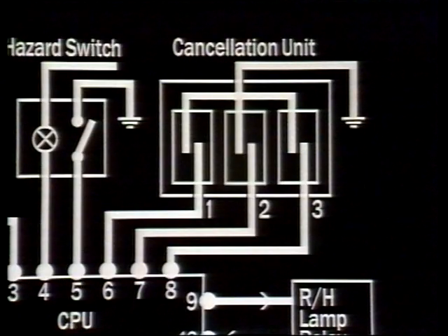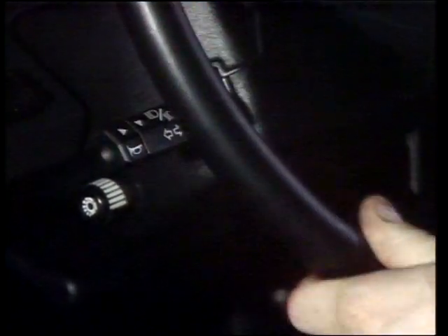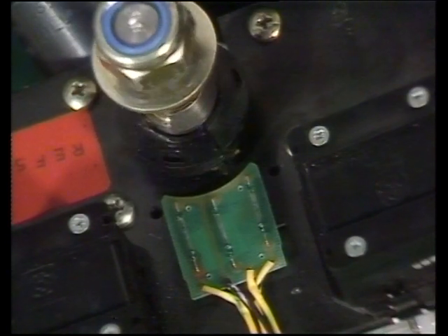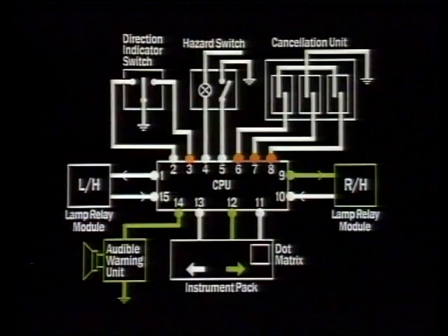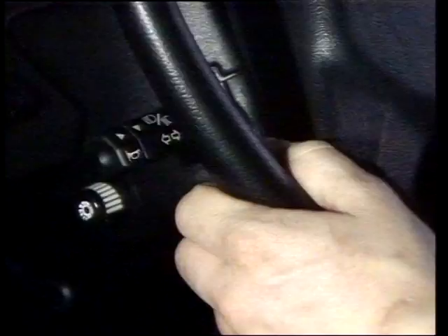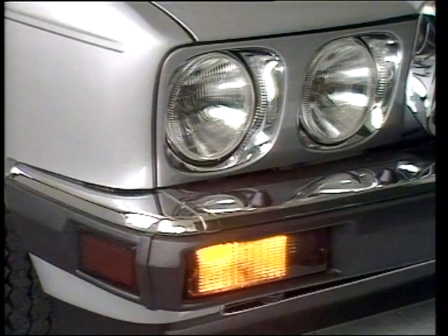The CPU knows that if the reed switches close in the order 3, 2, 1, then the steering column is being turned to the right. When the steering column is straightened up after turning right, the magnets pass back over the reed switches, closing them in the reverse order, 1, 2, 3. The CPU then knows that the maneuver has been completed and cancels outputs to all indicator accessories, thus cancelling the right-hand turn signal.